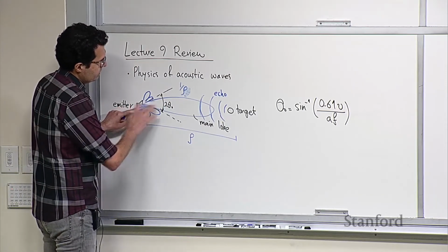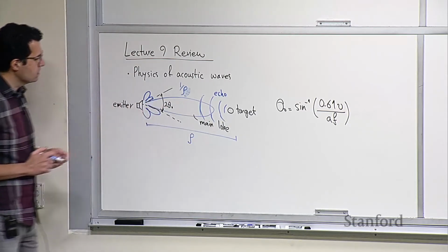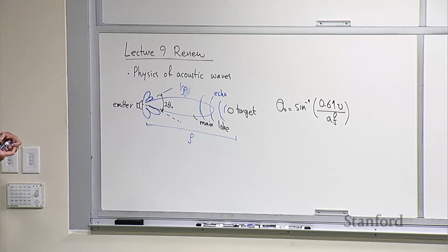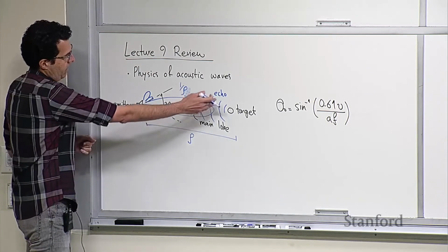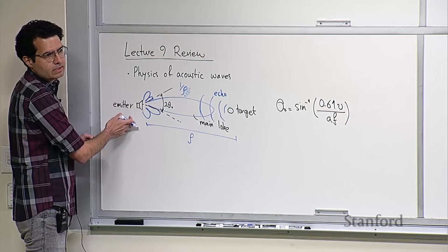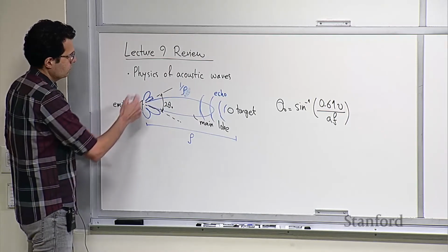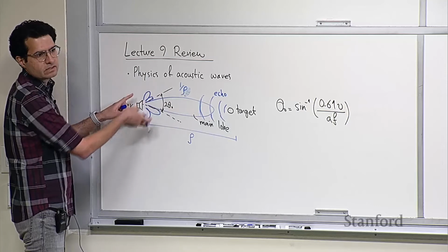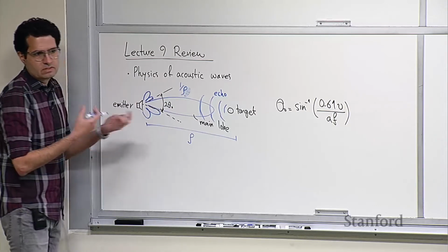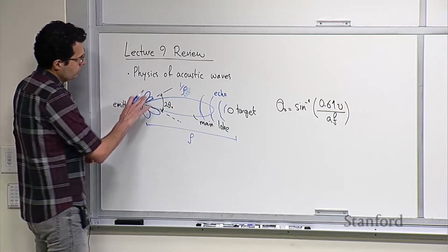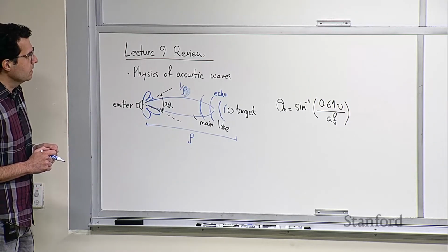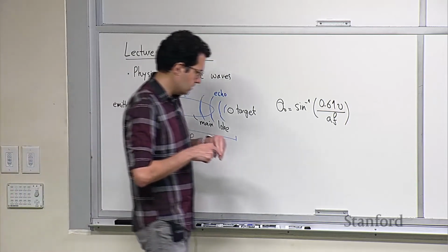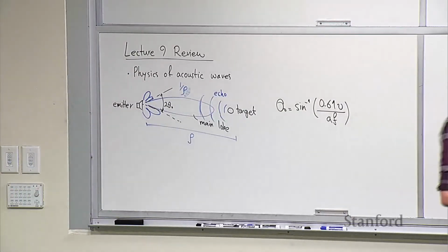And then we said that most of these components can operate both as a transmitter and a receiver. So if you have one of those transducers, then for collecting back the echo, the sensitivity of that is going to have the exact same angular pattern as the transmit, because it's the same physics, basically. So then you get the same Bessel function as your sensitivity. Maybe I should go to this slide here, because we can also look at the expressions together.